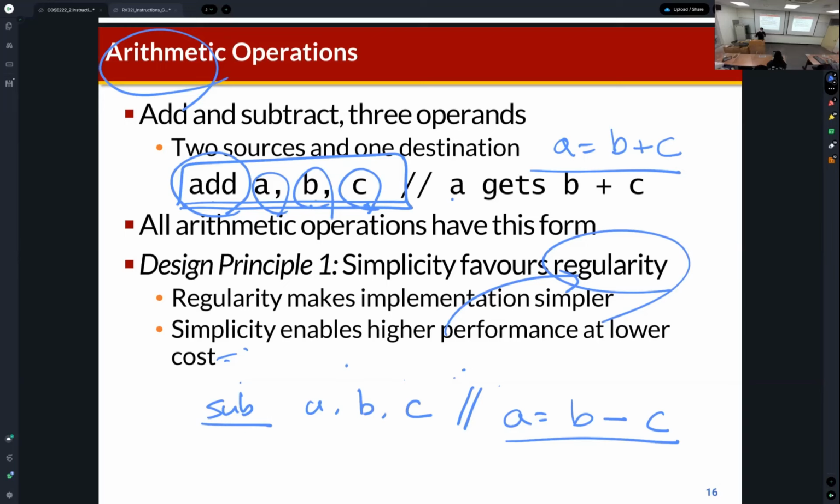Which means that the frequency becomes low, we need to use a low clock frequency, because the hardware is complex. And when we consider the performance of a processor, performance depends on the instruction count, CPI, and clock cycle time.